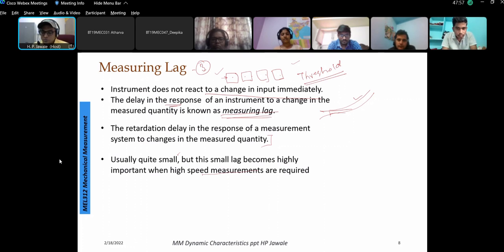Suppose the application is filling 200 gram jars. Until the weight measures 200 gram, the inlet valve will be open. As soon as the sensor gives the signal that 200 gram is reached, it will stop the supply and the bottle will move ahead.